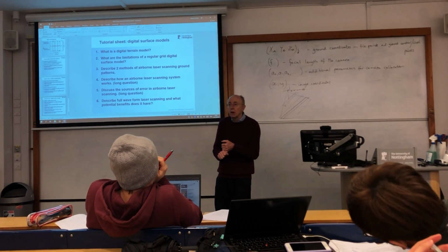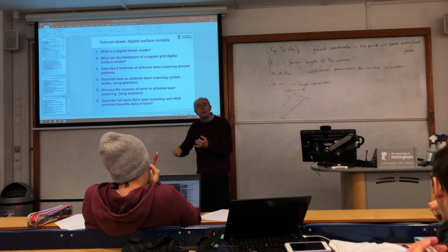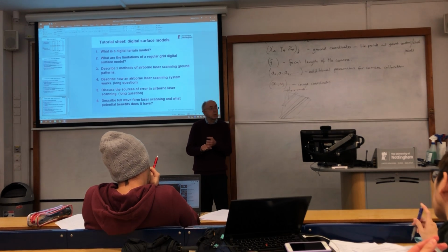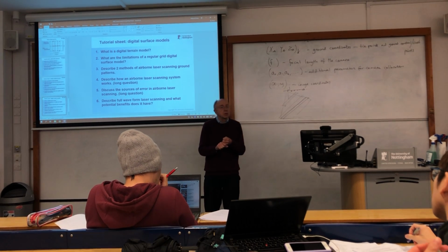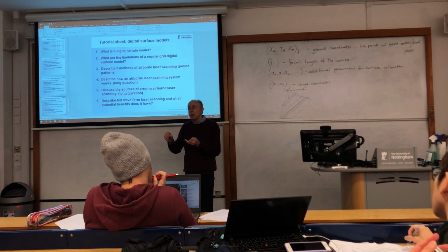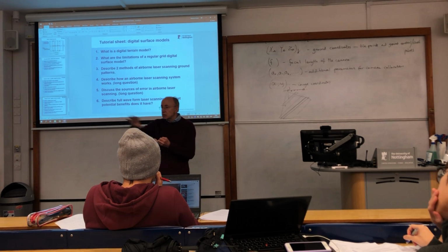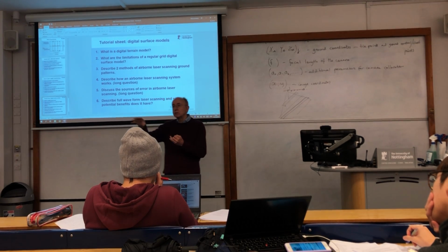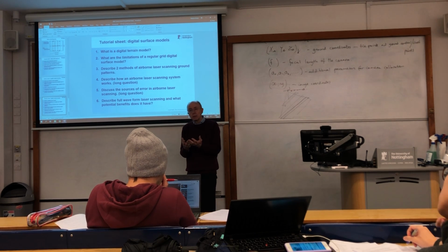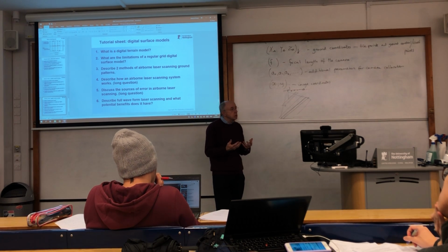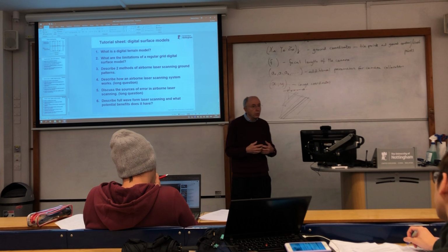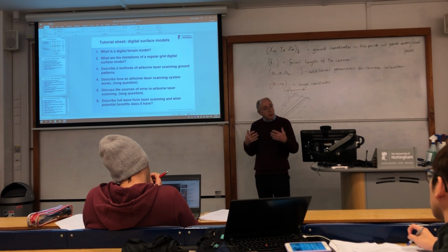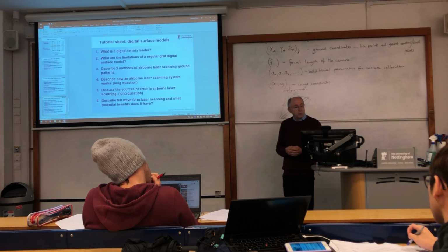It's not picking up a point on the grid. Photogrammetry, when you do the image matching to get the digital surface model, is not picking up a point on the grid. It's picking up object points and then you interpolate. So a grid, whilst looking very good, can sometimes be from an interpolated model.